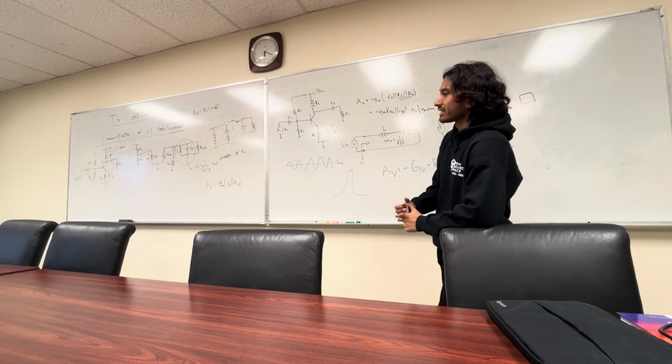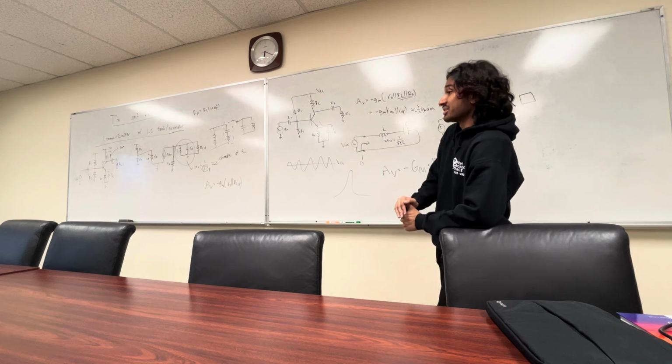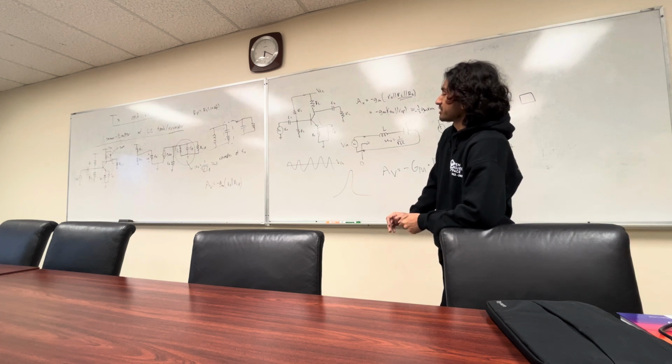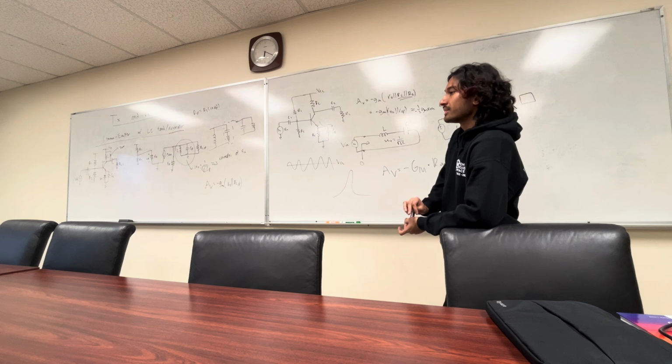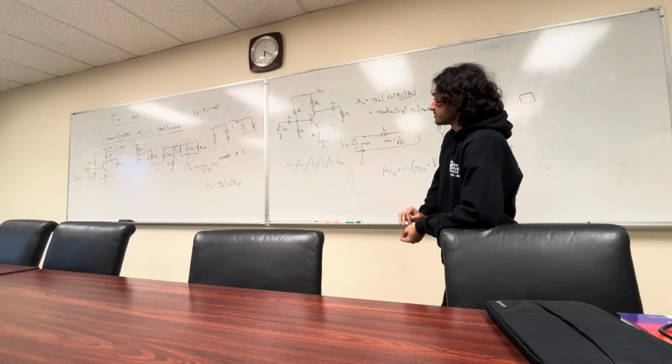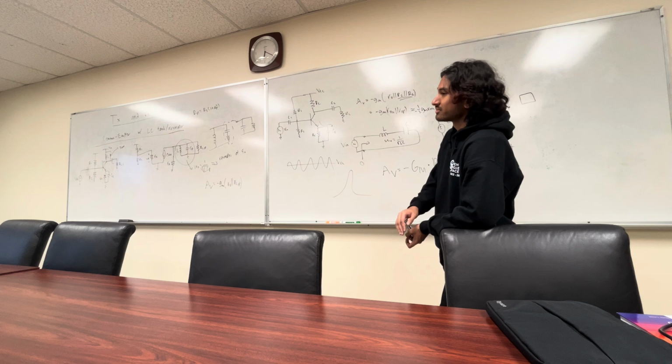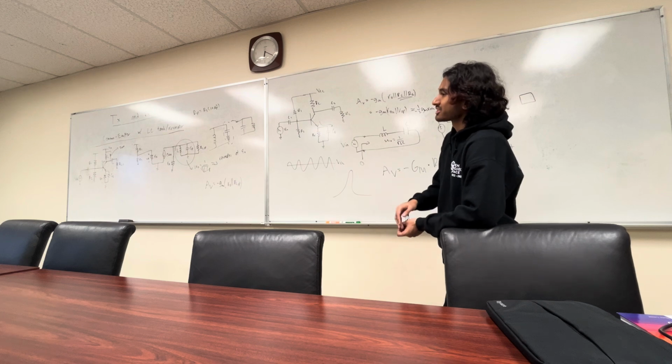Active loads and I guess cascodes are probably something you could do for amplifiers. For RAP, is it necessarily worth it? I don't think so. It's something that would be interesting, but it's also a lot harder to teach. And that's the reason why we just have very simple common emitter stages, Class A amplifiers.